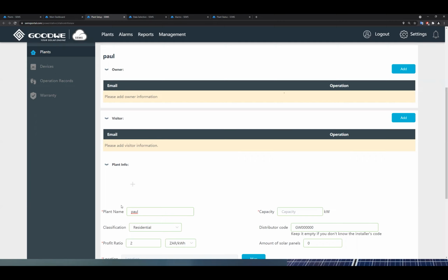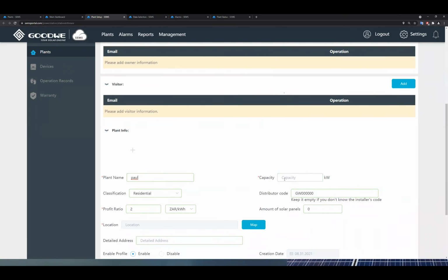So in the domestic situation, sometimes when you hang the inverter on the wall and you're going to come back tomorrow to commission, the end user is too curious and registers his inverter himself. So that does sometimes happen. That's why it might be a good idea to already add the device to the plant so that the end user can't do that prior to your commissioning. Once you're done and commissioned, you can simply come here, add owner, but we'll get to that now.